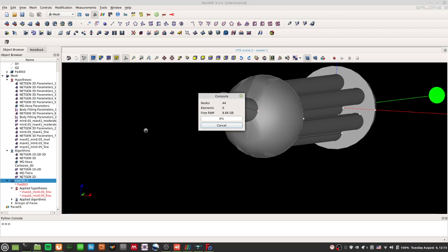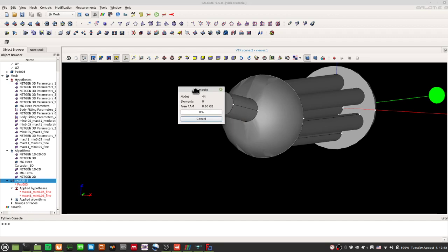It will be very slow this time because I increased the number of mesh elements by a lot, and that's how I actually generated such a mesh with 2 million plus points, which is not ideal. Okay, so it looks like this part's done. I have 130,000 elements for the 2D, which is way too much, in my opinion.